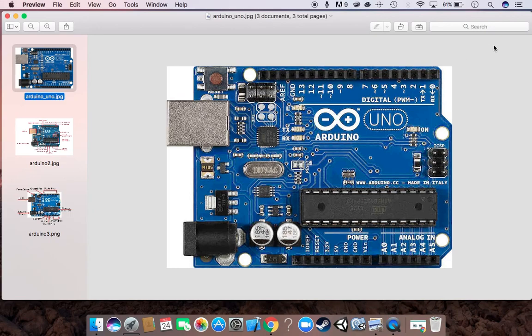The TX will transmit data from the Bluetooth module to Arduino. The TX of the Bluetooth module will be connected to the receiving pin of Arduino UNO, and then the data will be received by the board and then it will transmit data. It will transmit from this TX pin, and this transmission pin will go to the receiving pin of the Bluetooth module. I hope you get it. Otherwise in later courses we have explained it further.